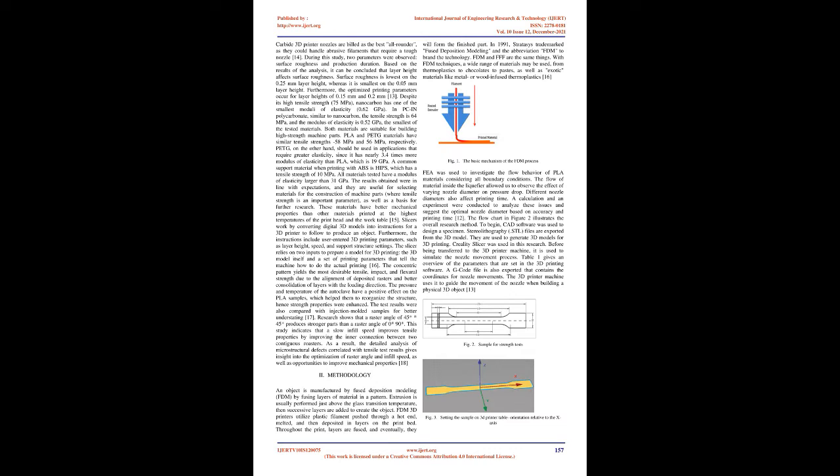Filaments with metal, carbon fiber, and glass additives are the best use of filaments. This is why Olsson created the Olsson Ruby. When combined with a ruby tip, a brass nozzle has the thermal conductivity of brass and the abrasion resistance of ruby, specifically aluminum oxide. A nozzle like the ruby is ideal for highly abrasive filaments, as with steel.